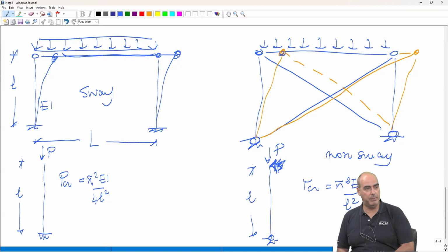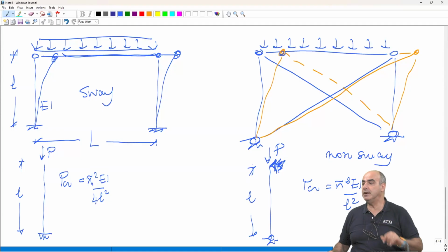But at a certain point, what happened? The code changed, like it happened in Italy after the 1985 snowfall. The snow loads have increased. You have designed this building for a snow load which is now 2/3 of what the code and the law prescribes.